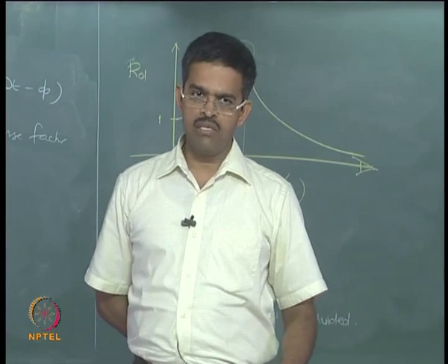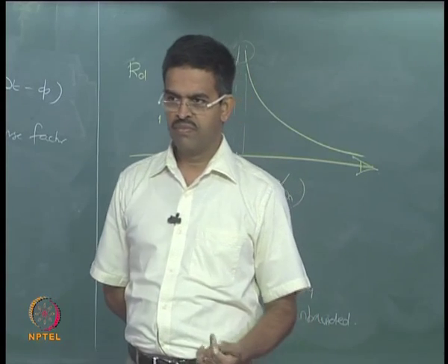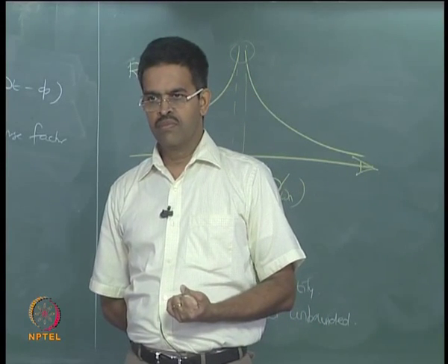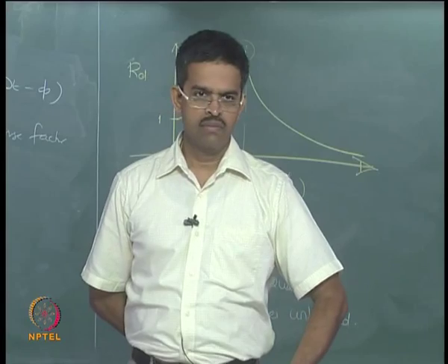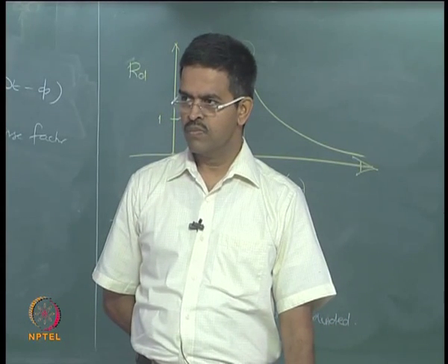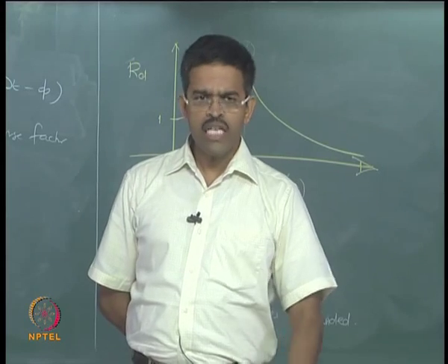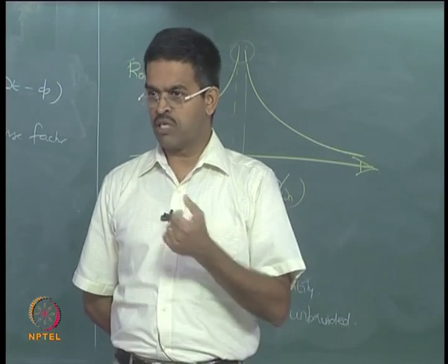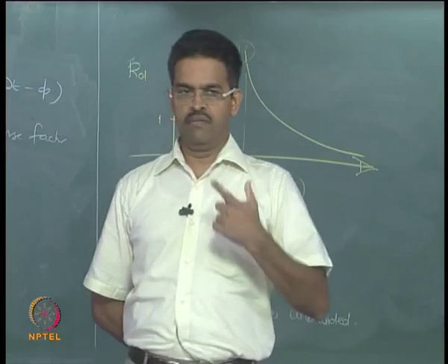When M alters, omega n cannot be fixed. Omega n is also varying in offshore structures specifically. Therefore, there is a very low probability, fortunately, in offshore structures that resonance will set in.